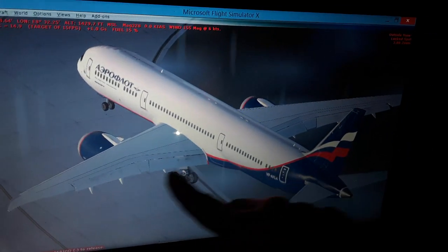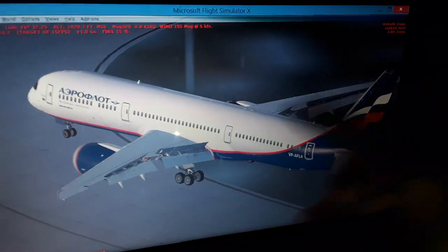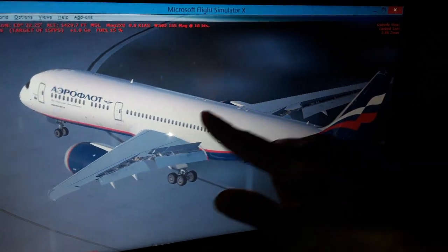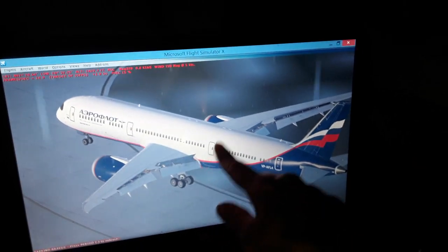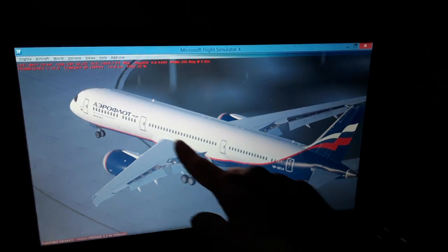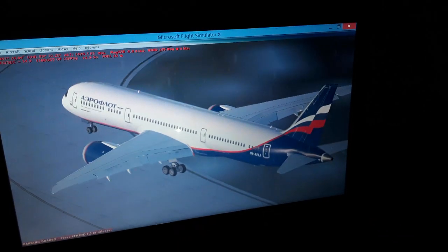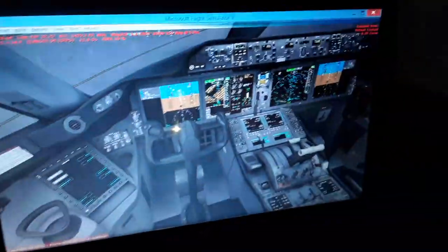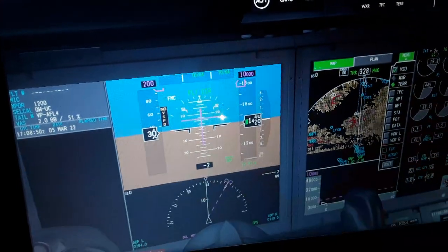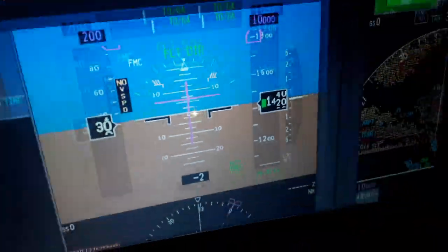So we have the left and the right wing fuel tank, and the center tank over here. Also we have them in aerodynamic order, where the maximum aerodynamic lift occurs in the forward wings. It's also the position where the center of pressure is moving back and forth on the top surface of the wings. Also the airflow becomes detached from the top surface of the wings, and we have the wing stall in the air. For the stall, you will see the airspeed indicated here in the primary flight display. We're gonna have an amber, yellow and red color indication just below the airspeed when flying. It's gonna show us the stall speed and the angle of stall.